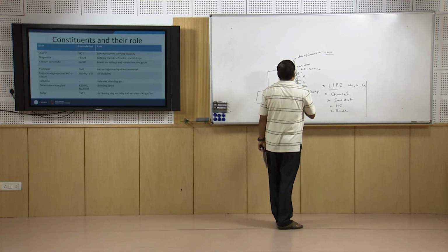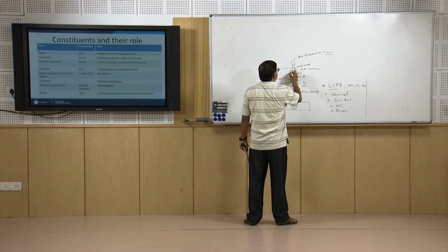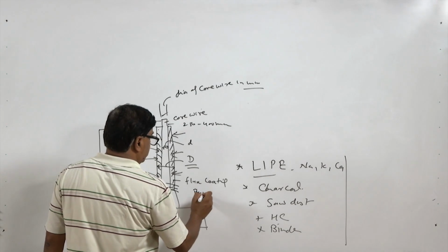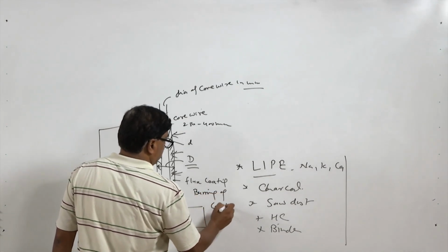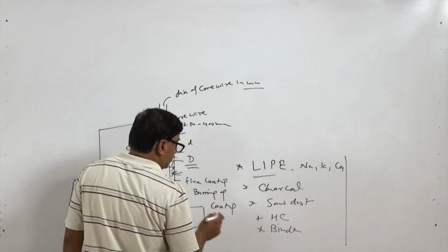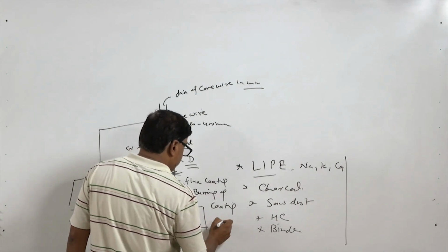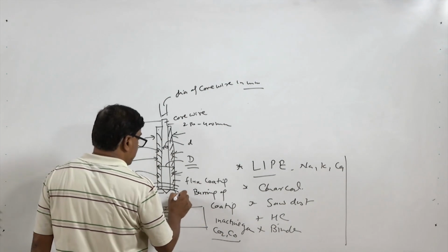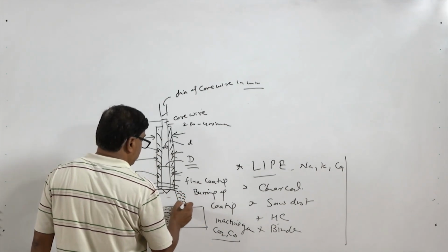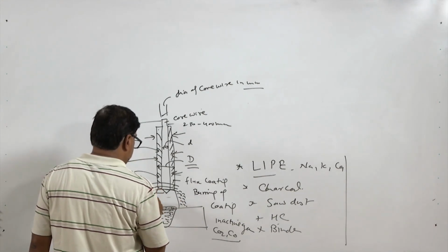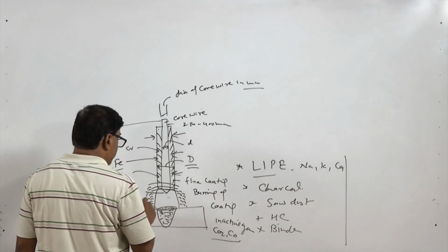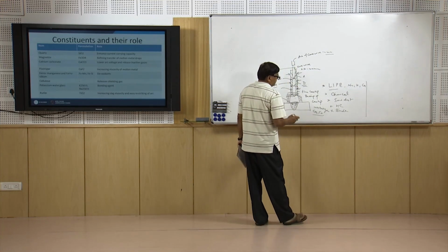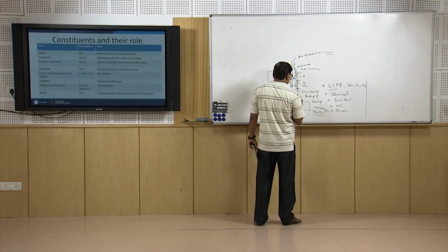One of the important functions of this flux is that when the coating approaches the arc in the course of welding, it is burned out. Combustion of the coating material produces a lot of inactive gases in the form of CO2 and CO. These gases are released due to the thermal decomposition of the coating constituents and combustion. These gases form a very loose cover of CO and CO2 around the welding arc, and thereby help in protecting the weld metal from atmospheric contamination.